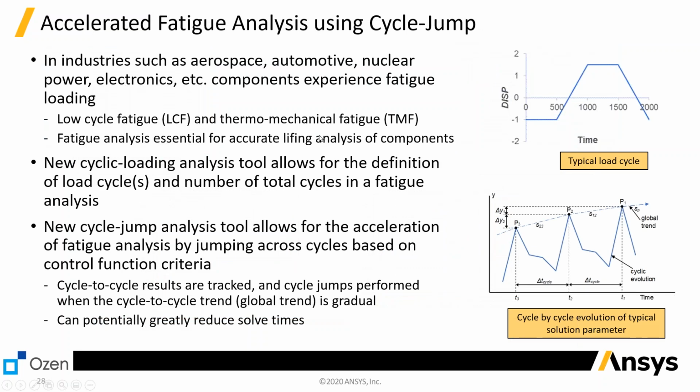For the fatigue analysis, we know that in fatigue analysis, you need to use a load cycle and you have to repeat that a lot of times. But now we can use what's called accelerated fatigue analysis using cycle jump. Basically, a new cycling loading is used, and that will help to maintain the same performance, but will need much less number of cycles to solve the problem.